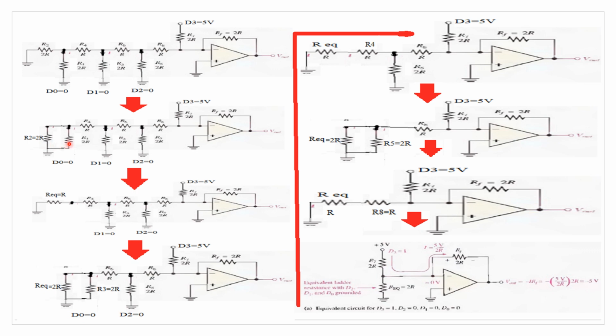2R parallel 2R. So these two resistors can be considered as a parallel circuit like this. 2R parallel 2R. We all know that when two resistors are in parallel, its value will get halved. So here the equivalent value will be half of 2R, that is R.